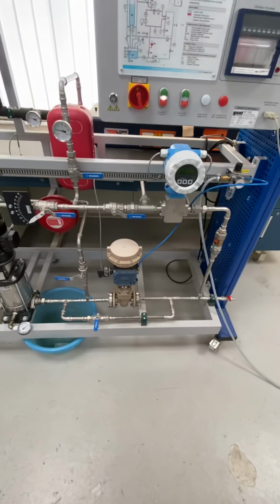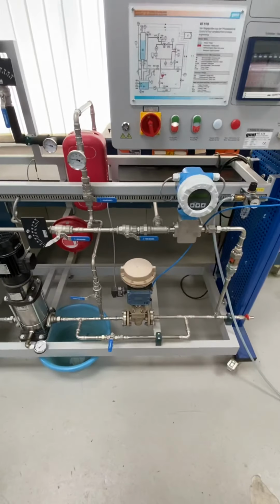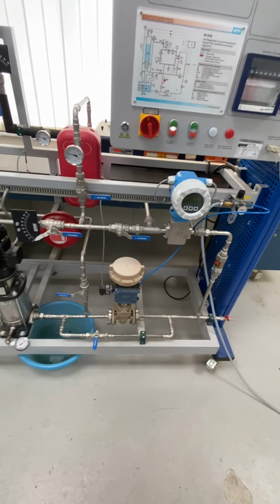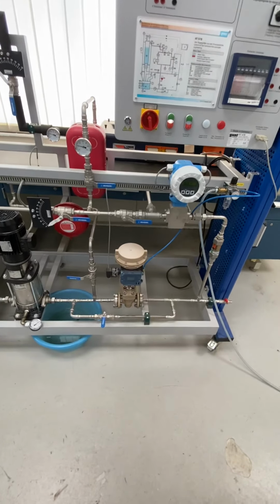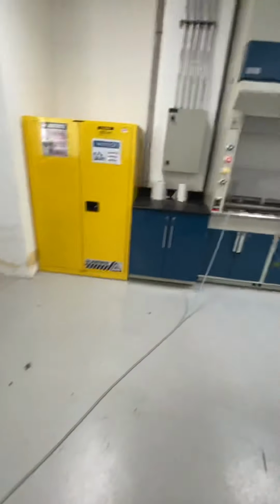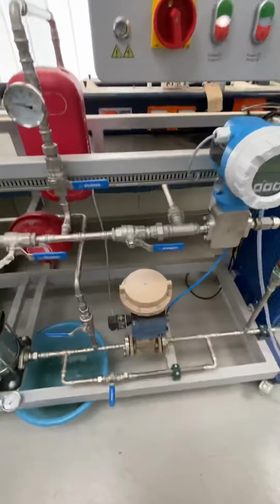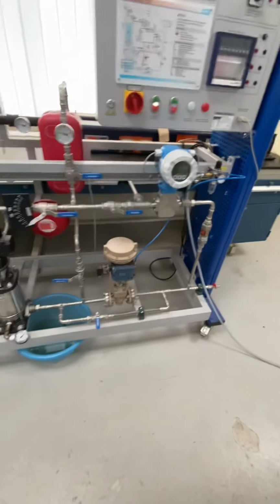Now for the control valves, the control valves are designed to have what is known as the fail-safe position, which is basically the original position of the valve. Some of the control valves are originally designed to be in a fully closed position, and the supplied air to the valve will open the valve. So an originally closed valve, or a failed closed valve, is also called an air to open, because it is originally closed and you are supplying air to the valve in order to open it.